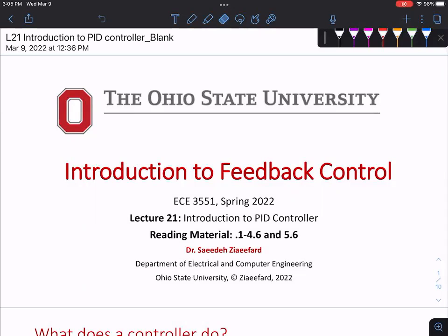You work with transfer functions, you know how to deal with steady state error, and what type of system can handle what kind of input to give us a steady state error of 0 or a constant value, or they would not track. You know how to evaluate the system to see if it rejects a disturbance and if it can track an input. Meaning that if we have a desired value, can our system track it and get to that desired value? That's what tracking means, right?